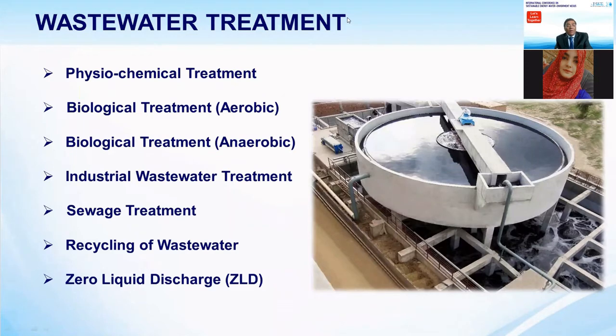In both cases, we have to meet the inlet conditions of the aeration tank, wherein we have to grow the microbes, bacteria, which will digest or decompose the biological and chemical contamination, which is represented by the biological oxygen demand and the chemical oxygen demand. For that, it is mandatory that we must bring the temperature below 40 degrees centigrade, and a pH from 6.5 to 8.5 is okay for the growth of the microbes, whether it is sewage or industrial wastewater treatment.